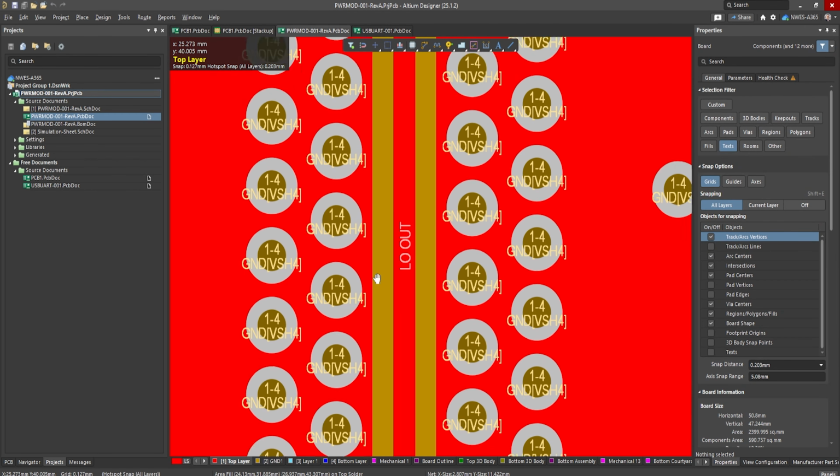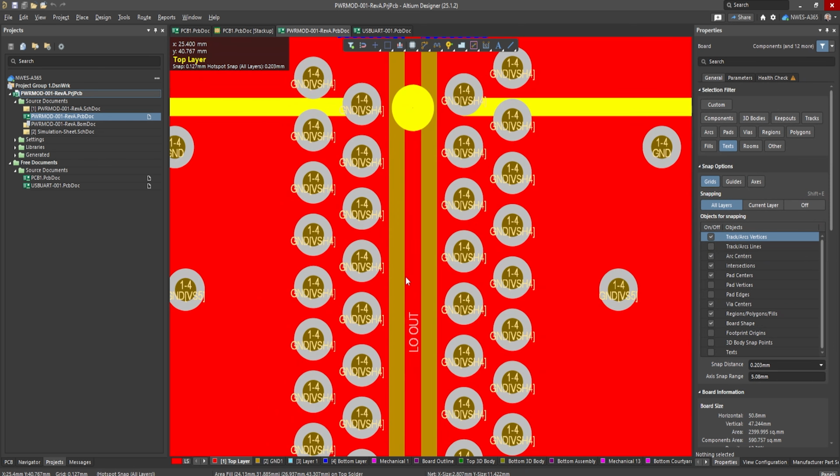So now that we know the factors contributing to the impedance of coplanar lines, let's take a look at some example calculations. First, we're going to look at an example calculation in Altium Designer. And what I want to do is consider a situation like this, where we have a single-ended line on, let's say, a 4-layer board, or it could be a 2-layer board. Regardless, you have ground nearby this line, and then we're going to calculate the impedance and see what happens when we start to bring that ground in closer.